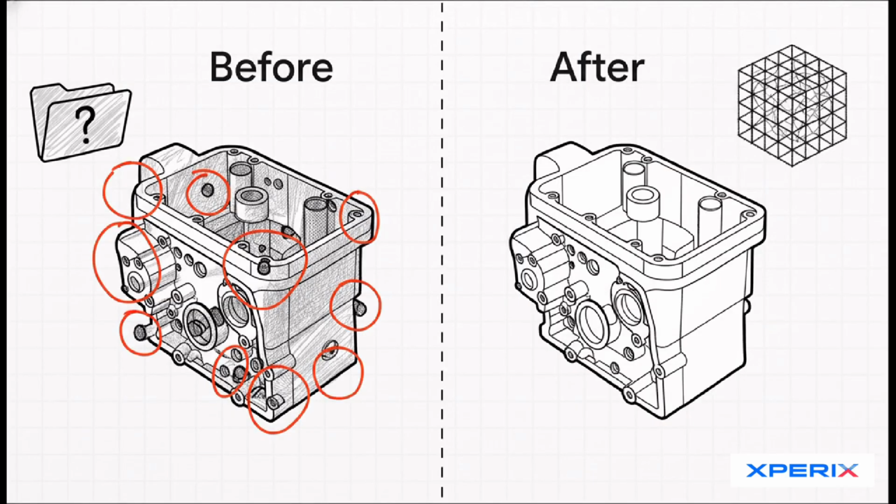This tool is an absolute lifesaver, especially when you're getting a model ready for manufacturing or for some CAE analysis. You can just grab holes, fillets, chamfers. You can grab entire features and just hit delete. And then NX just automatically heals the surface where that feature used to be. The payoff here is massive. For cleaning up imported models, this can save an analysis engineer hours, heck, sometimes even days of just tedious prep work.